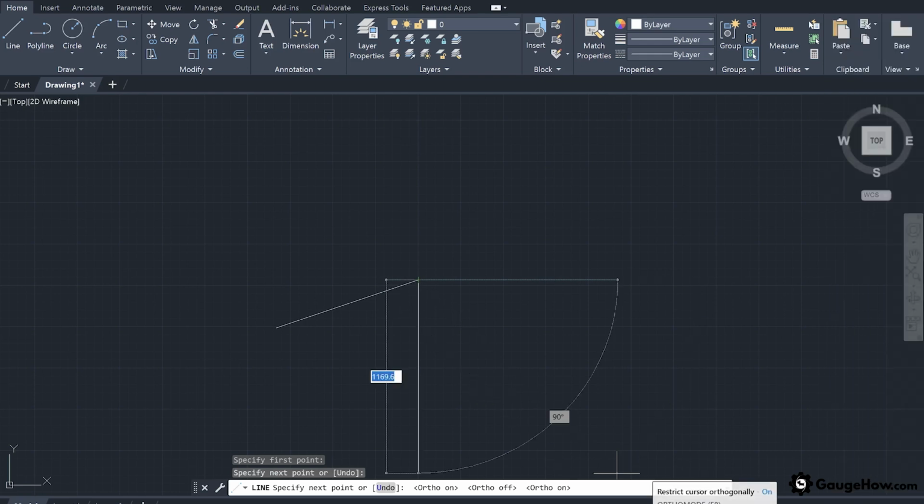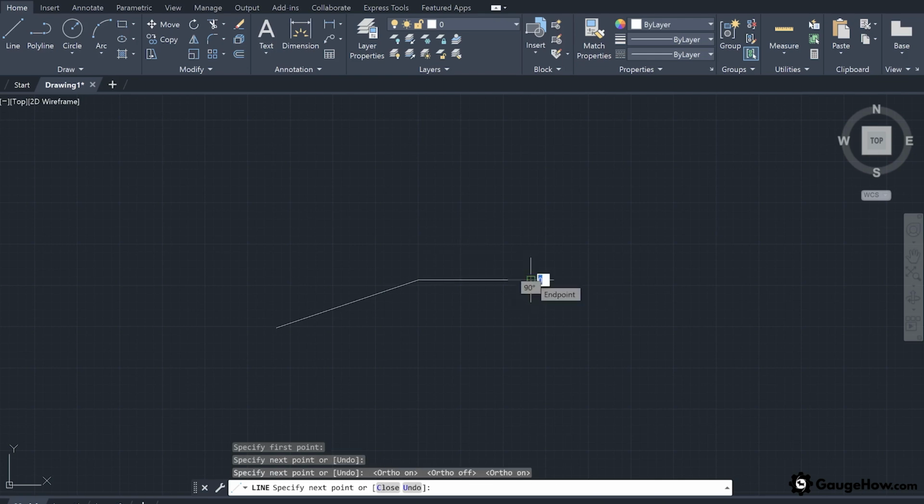Now once you click it, and if you try to draw the line, there will be only two options available: to draw it in horizontal direction or in vertical direction. Now let us first draw it in horizontal direction. Now again, if you move in upward direction or at any angle, you will see that it will allow you to draw only for 0 degree, 90 degree, 180 degree, and 360 degree.